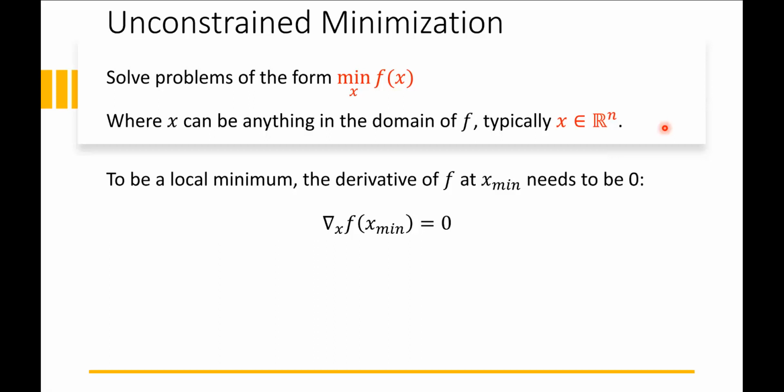So great question in the chat. How is this distance even figured out? If the robot knew the distance away, wouldn't it be able to just fix itself? So the distance is in end effector space, right? And there's some non-trivial mapping between our joint configuration, right? So what angles each of my arm motors are, for example, and the end effector position, the Cartesian coordinates of the hand. So it's not really clear how changing my motor angles is going to actually get my hand closer to where I want it to be.